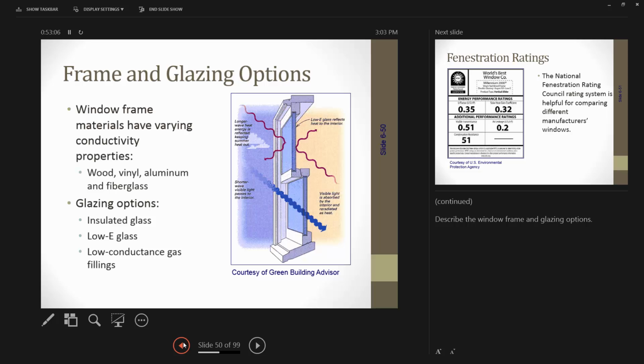We'll put it on S3 because we're trying primarily to take advantage of the heat gain and hold that heat in. If you're primarily in a cooling climate, windows will be manufactured and they'll be putting that low E surface towards the outside. Sometimes they'll use a hard coat on the outside. But it does make a difference and increase the thermal performance of the window.